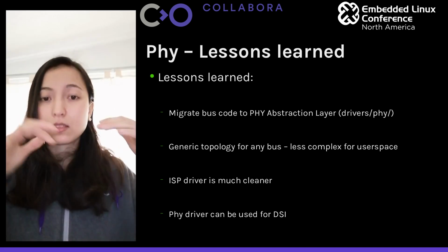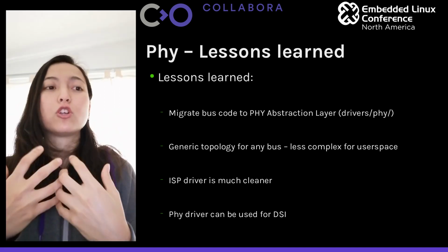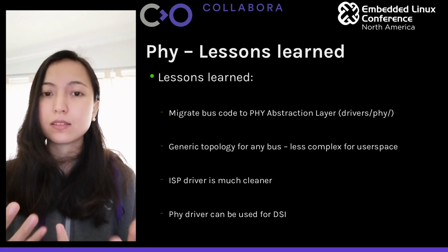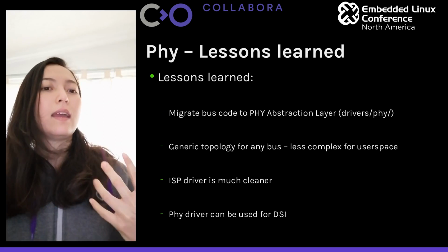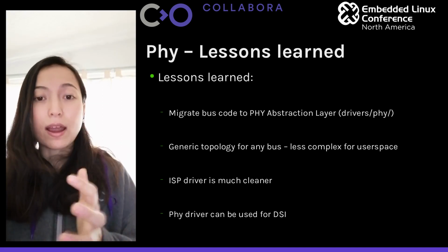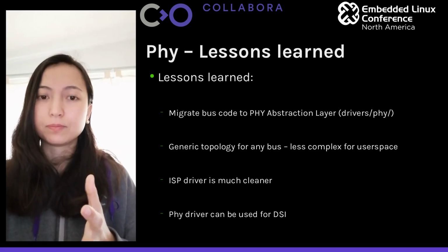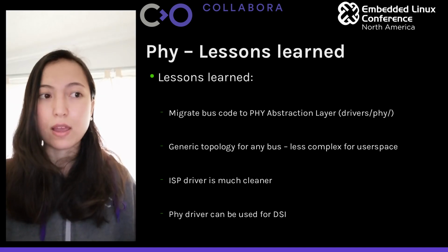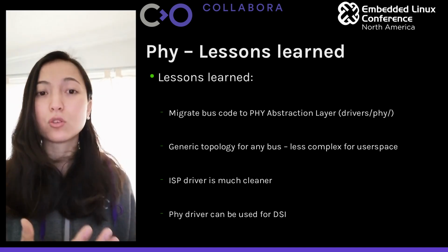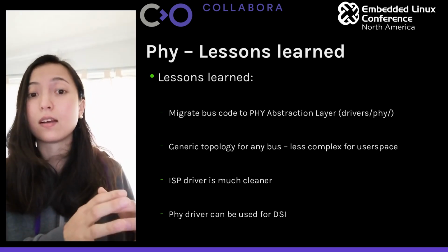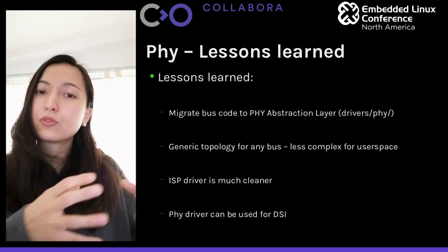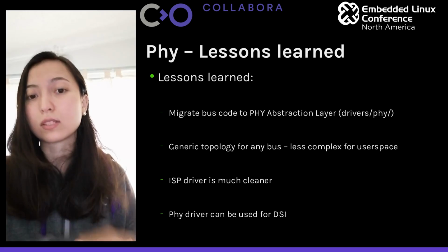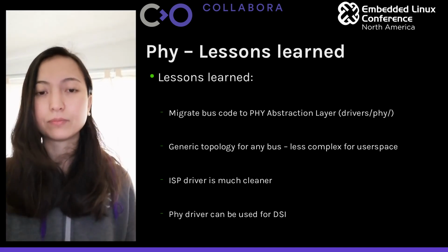Then with this, you will have a more generic topology for any bus. It is less complex for user space. And the ISP driver itself becomes much cleaner since you separate those 2 drivers. And the PHY driver can be used for other protocols as well, for DSI, for instance, if you can have both protocols under the same line.